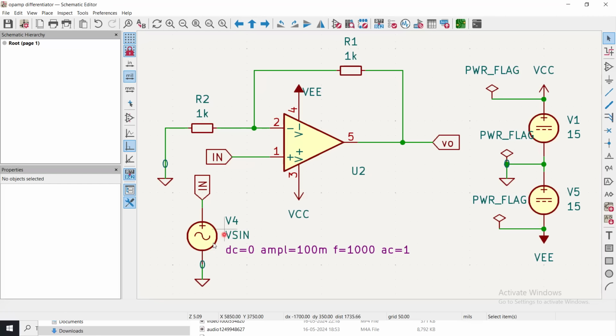So remember, a DC voltage source, if used, can be used to analyze the DC performance and the operating point of the circuit. If I use a time varying voltage source, it can be used to understand the time domain behavior of the amplifier. For example, I have a sine wave at the input with the gain provided by the circuit.